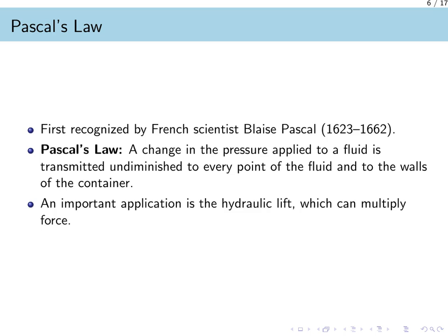Since pressure equals force divided by area, that same pressure acting on a much larger area produces a much larger output force. Essentially, Pascal's law allows a small input force to generate a large output force, forming the basis for hydraulic brakes and car lifts.